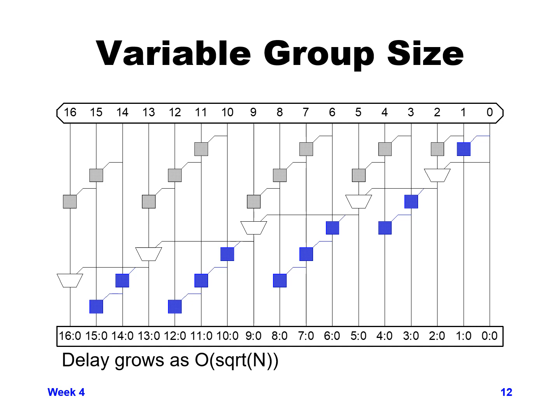Even though it's a little bit more complex to create, since instead of creating one group that's the same for every group of bits, you now need to create variable length PG. Your generate equations are going to be a little bit more complex because you're going to need a larger variety of them. So it trades off better delay for a little bit more complexity in your design.